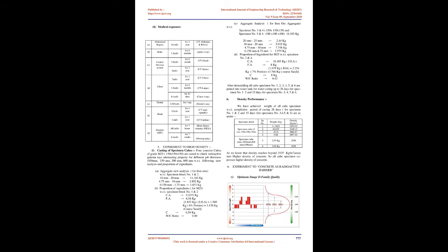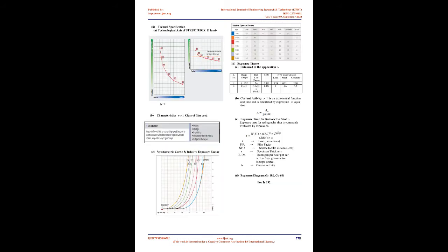5. In order to prevent fresh concrete from segregation, the mixing duration was kept as low as possible. 6. All concrete specimens were cast in 3 layers into 150 x 150 x 150 mm cubic steel molds, each layer consolidated using a vibrating table. 7. After casting, concrete specimens were covered with plastic membrane to avoid water evaporation and thereafter kept in the laboratory for 24 hours at ambient temperature. 8. After demolding, concrete specimens were submerged in a water tank until the time of testing.